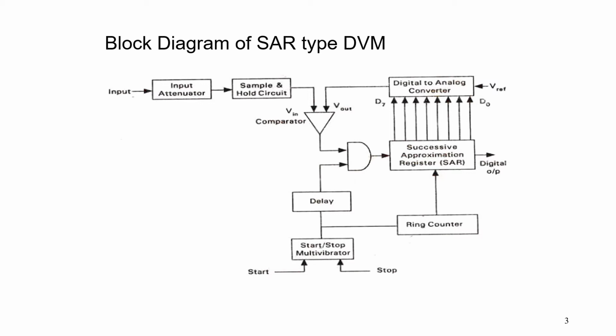Any digital voltmeter is capable of measuring analog DC voltages. However, with appropriate signal conditioners preceding the input of the digital voltmeter, quantities such as AC voltages, resistances, DC and AC currents, temperature and pressure can also be measured.